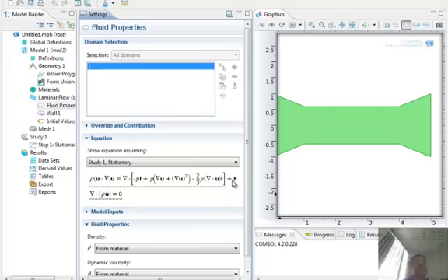You should be able to understand what each one of those terms are. What is the term on the left side? That one. The inertial term. And this is the pressure. This is the viscous term. Okay, and this term is 0 because it's incompressible flow. Okay, and F is any body force, gravity or any other external force. And this is your continuity equation. Now they have allowed density to be inside that, but if density is constant, that will drop out automatically. Okay, so this is the equation you are solving.